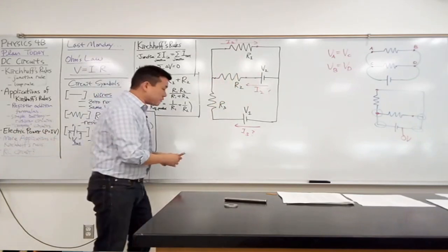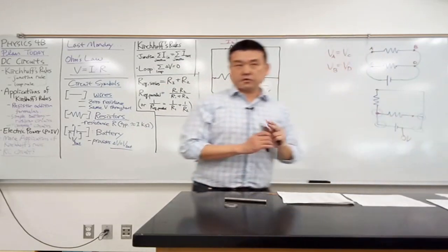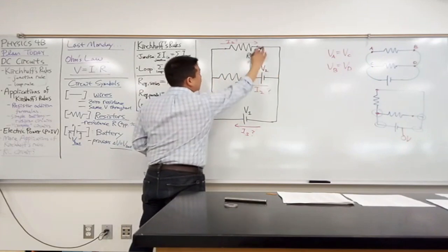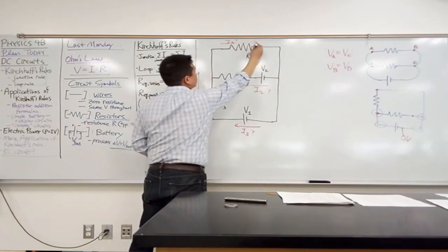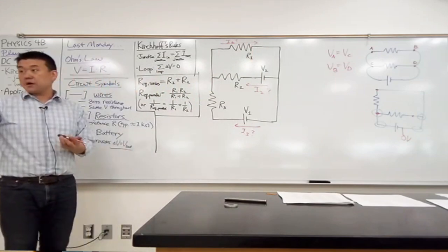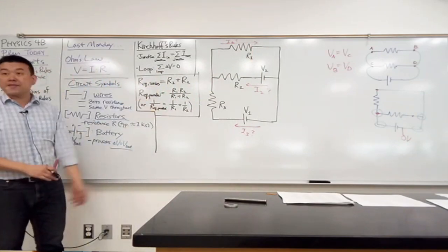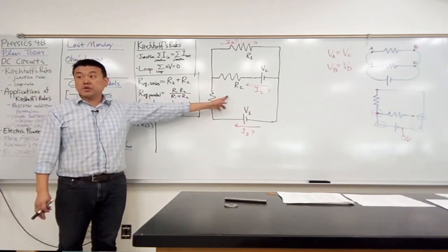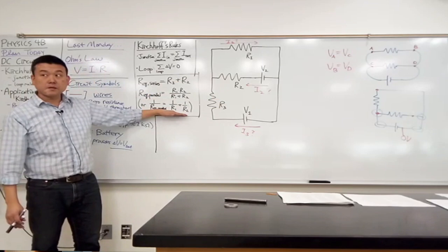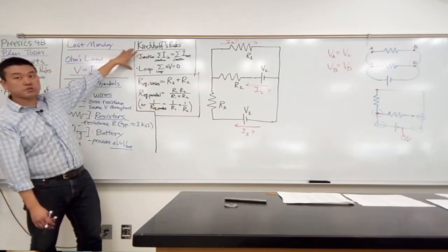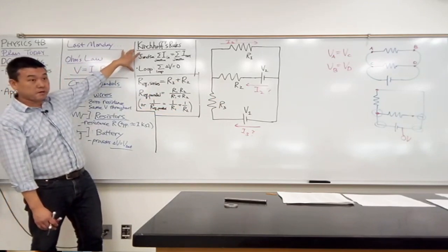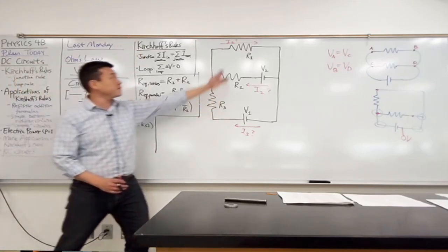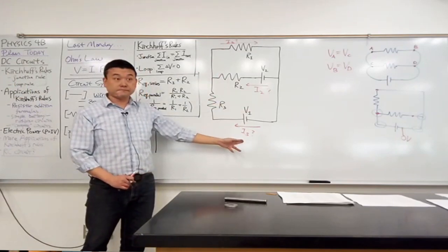So this is a good example of a general circuit that you might have to solve, where your circuit elements are not in series or parallel with any other element. So if all your problem-solving tool was this, something you might have learned in high school physics, then you're kind of stuck here. There's no tool that you can use here that's based on these two. But if you know the very basic circuit solving tools, we can go back to here. Come up with a system of equations, and then solve the system of equations to find I1, I2, and I3. Good?